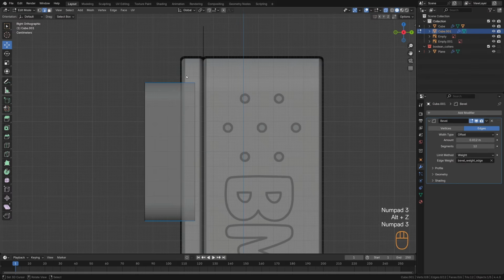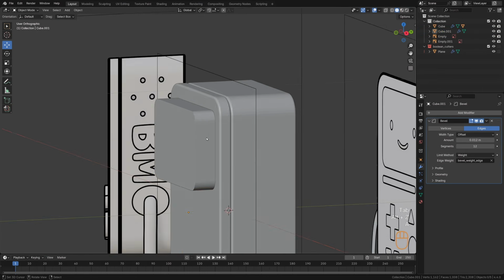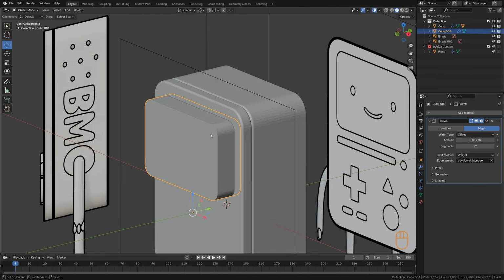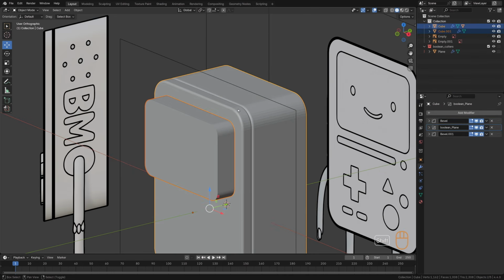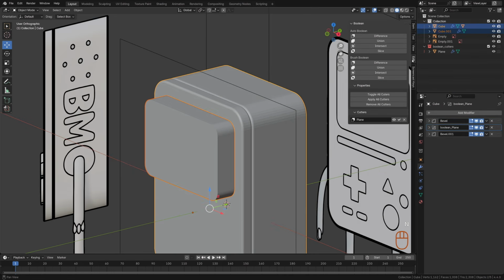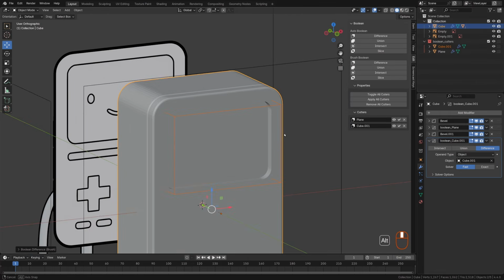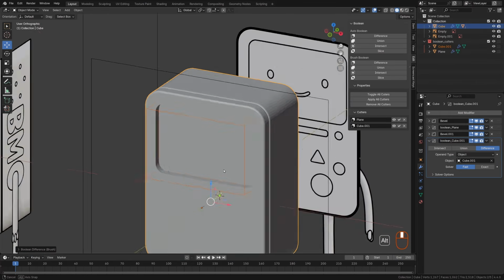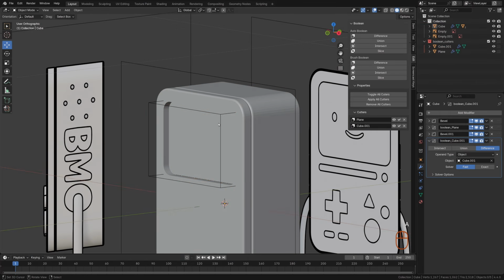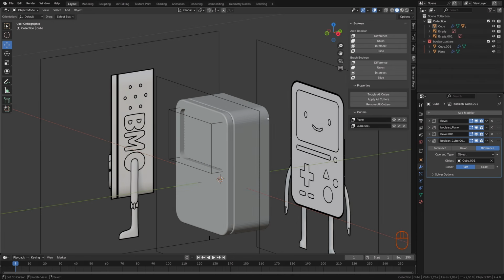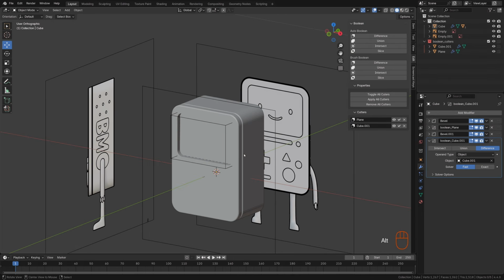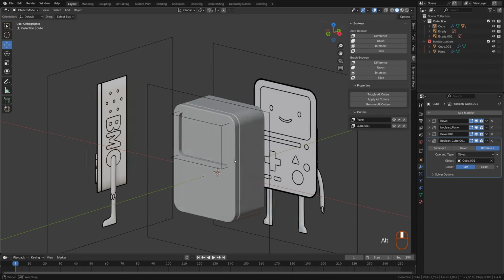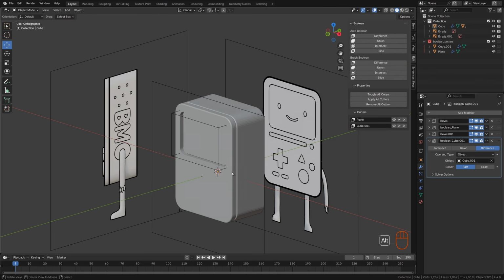Once you're happy with that, double check the depth. That looks fine too. Now I'll select the screen cube, then Shift select the body, and again go to Edit and apply a difference operation. That removes the entire front section where the screen goes. So that's how we use Boolean operations. Mainly to subtract parts of an object's volume, using another object.